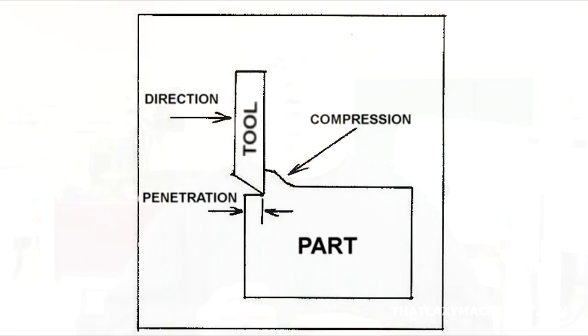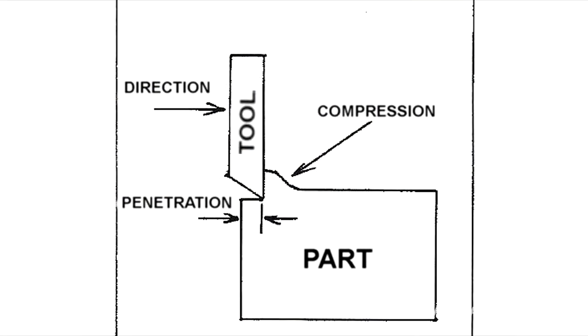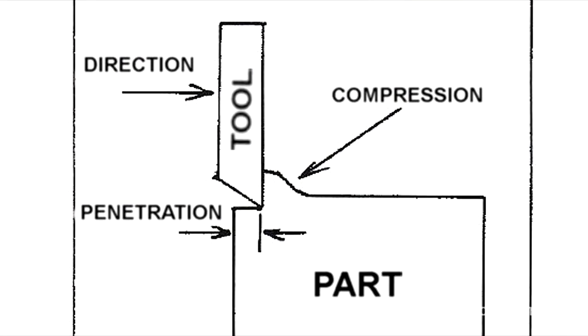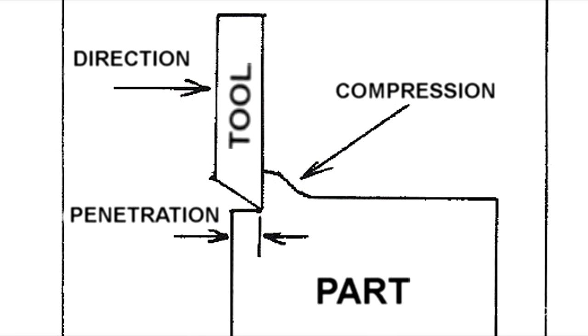Penetration starts at the moment when the tool engages the workpiece. At this point, the tool is just trying to plow its way through the material, pushing it forward at the same time. This plowing motion applies huge constraints and forces onto the tool. At this point, the tool could fracture, especially if we were a little ambitious with the depth of our first cut. The second part of chip formation is accumulation.